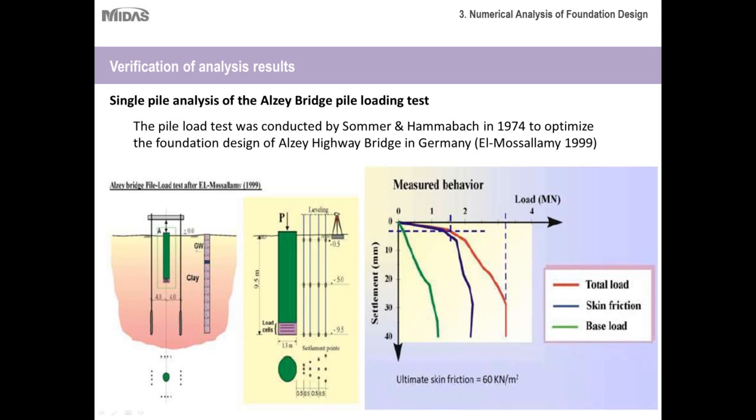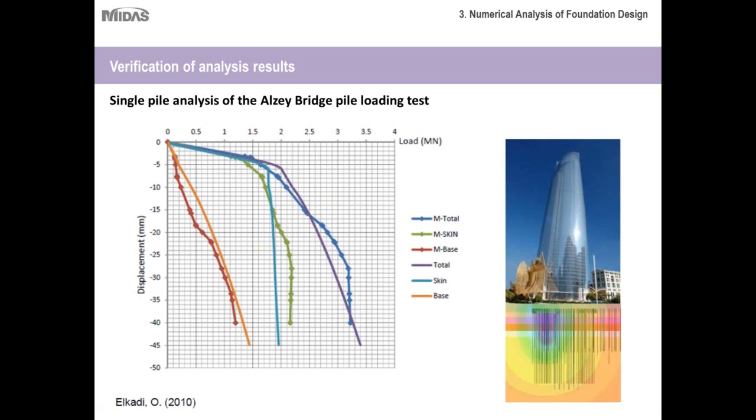Now we know that most of the time when we are dealing with pile foundations or deep foundations, we analyze or base our decisions on the skin friction value, because not every time we are able to perform the base load test on the piles. But if you are dealing with a pile which is strictly an end bearing pile, then this becomes more critical.